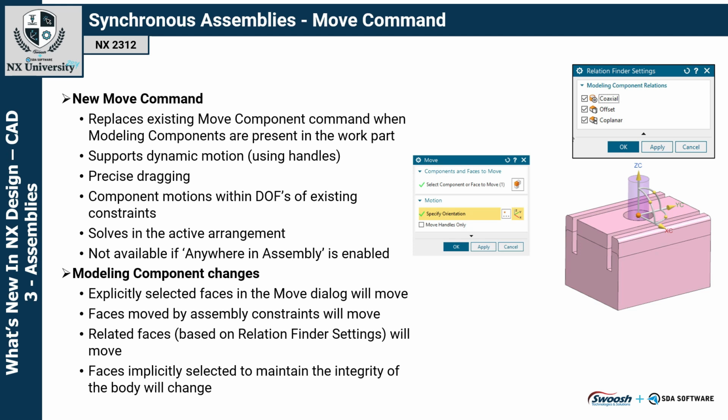Modeling component changes related to this. Explicitly selected faces in the Move dialog will move. Faces moved by assembly constraints will move. And related faces based on Relation Finder settings will also move. Faces implicitly selected to maintain the integrity of the body will also change.